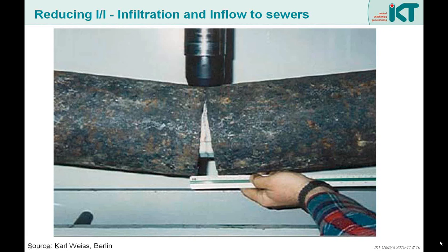One solution to the problem could be to reduce the bonding effect between liner and host pipe to such a degree that the liner will slide before cracking. On this slide, you can see a typical test for liners and gas pipes. For these pipes, movements of the very long old pipeline may cause very large crack spans that can definitely only be bridged by a sliding liner.